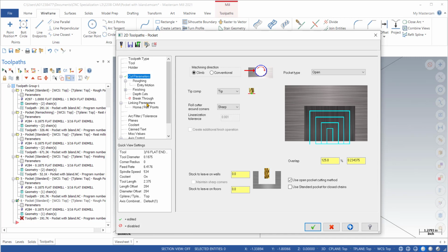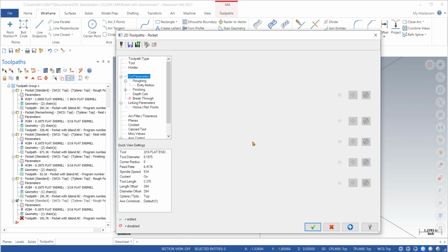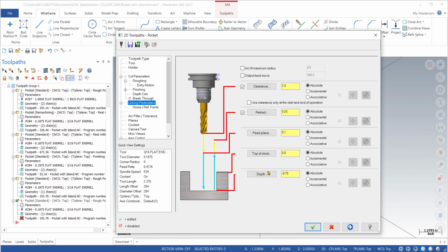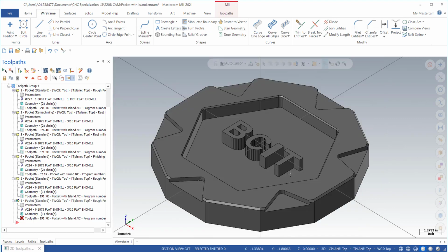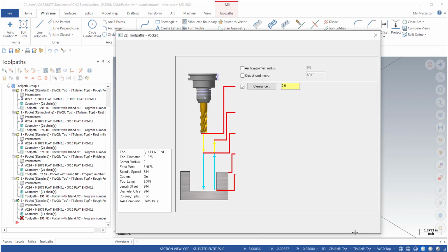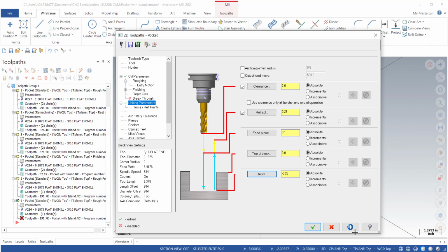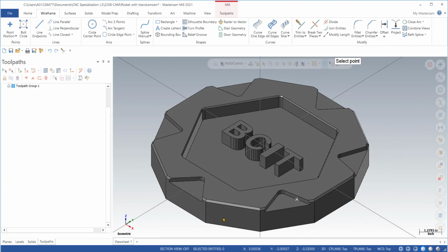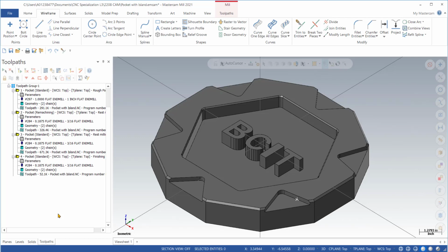The only thing is the depth. Those cuts are not that deep. So again, I will pick the depth with the depth button, and we wanted to go, yeah, this deep, somewhere here. Okay, so that's only 0.25 deep. All right. Yeah, so that's how an open-ended pocket can be done, and we can add it into the operations.